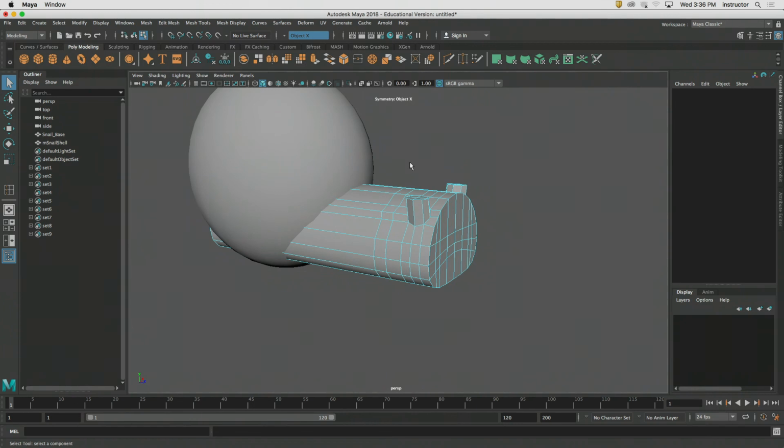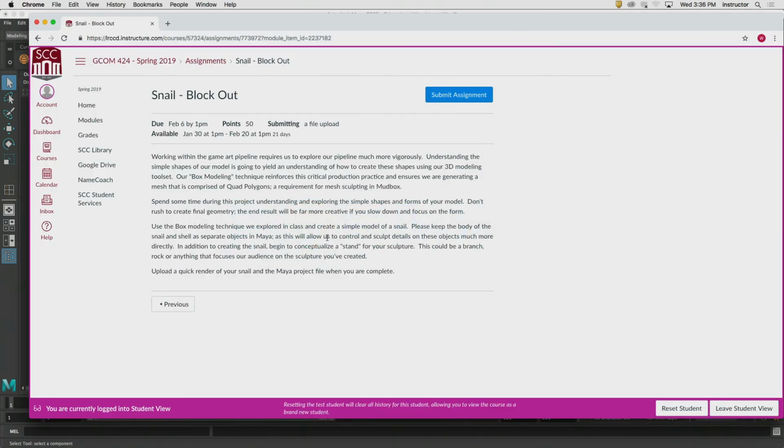Okie dokie, let's go back to your assignment real fast. So quad polygons, that's a hard requirement for the next stage of this, okay? You have to go through, and you really need to be disciplined with your removal of triangles from your mesh. That's going to be a barrier over in Mudbox. This isn't Pat just enforcing these ideas. It's fundamentally going to stop you in your tracks over in Mudbox, okay?